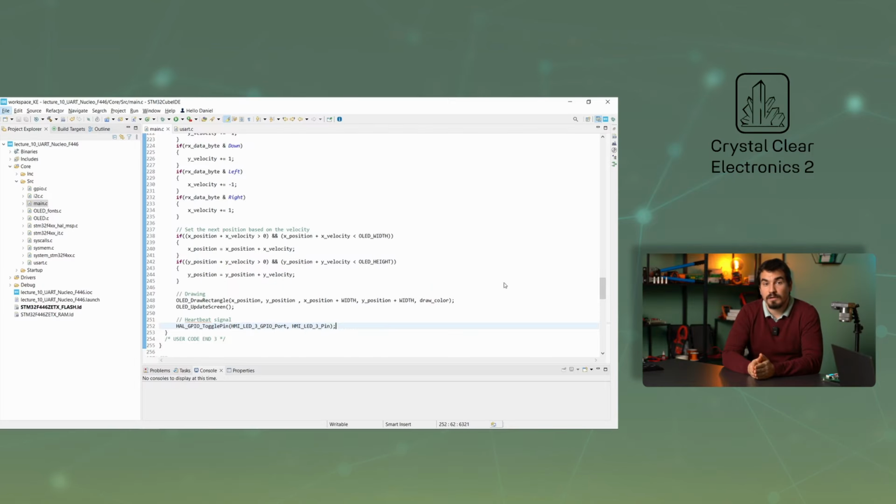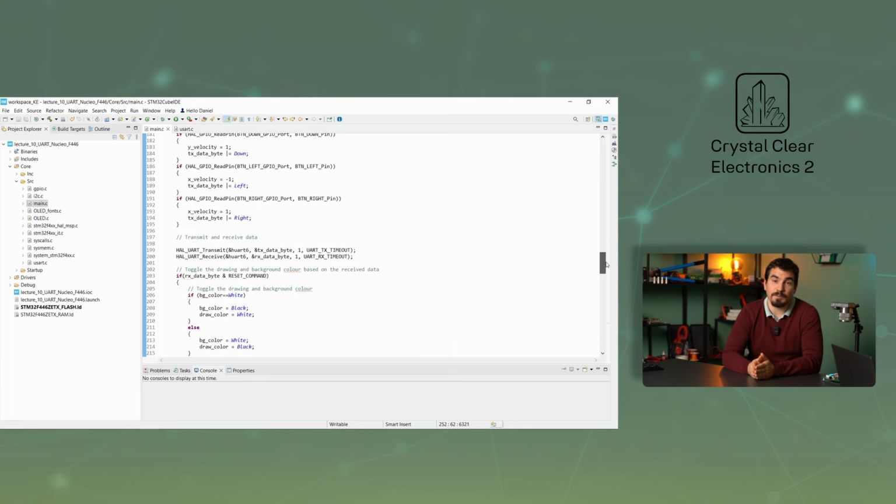The reason for this phenomenon is the HAL_UART_Receive function. An important parameter of this function is UART_RX_TIMEOUT, which is currently set to 200 milliseconds. This determines the maximum time the function waits for new incoming data. If information is received sooner, the function will finish, but in the case of a missing connection, no new message will be received, so the function will time out and wait for 200 milliseconds.